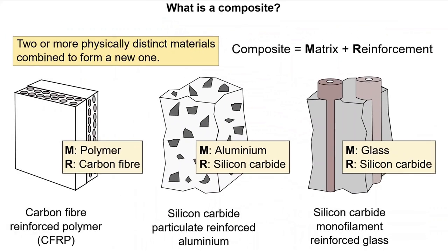All three of these examples of engineering composites adhere to our basic definition. One material is used as a matrix and another as a reinforcement. They are all unique in terms of their structure and arrangement. The ratio of matrix to reinforcement, the scale, and the orientation of the reinforcement are all different. So too are the choices of what material is used for each role, and the overall costs associated with their fabrication, processing, performance and service, and final disposal or reuse. Let's now turn to the material families that can be employed and the underlying strategy for employing composites.